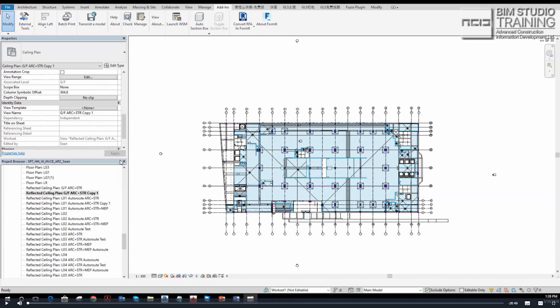From the engineering design point of view, you can size it. You know this area, you know the use, then you can calculate the cooling load. So you need a certain size of duct to carry a certain amount of cool air from A to B. We know that, so we know how big the duct should be.